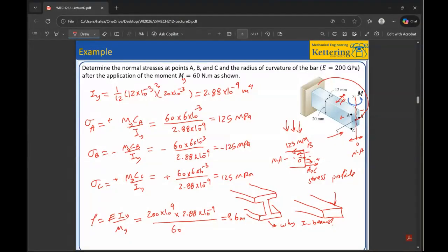It is reduced weight. That's the reason, right? Same thickness, but with less material. Not just because it has the same thickness, but because it has almost the same strength, as Wasi said more completely. So we learned that sigma equals MC over I. And no matter what the geometry is, this M remains the same. That's the load that we're applying.